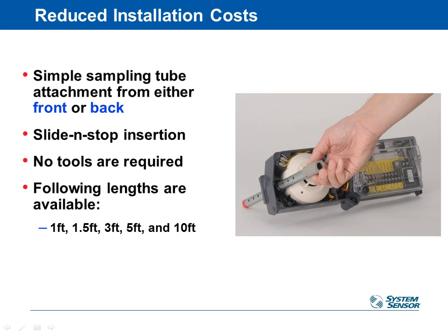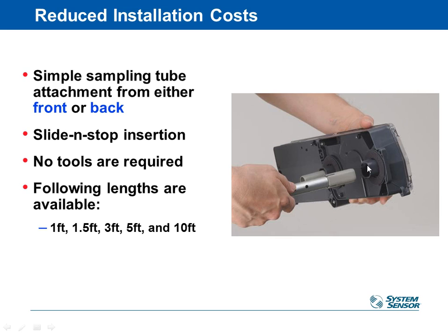As you can see there, the sampling tube for the supply side goes on the left hand of the detector. The exhaust one would go right under this gentleman's hand and it would poke through on that side. If you install it from the back, it would look like that. So here's the supply tube going in here. Airflow would be in the direction of these holes, blowing right into the holes, and then that would go into the chamber over here, and then the air would exhaust itself back out this little short one.